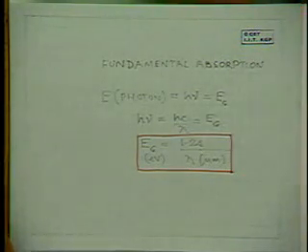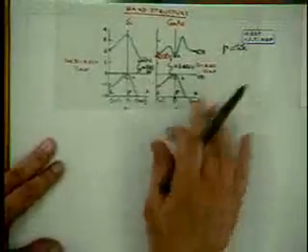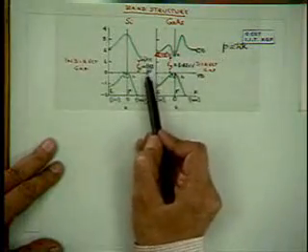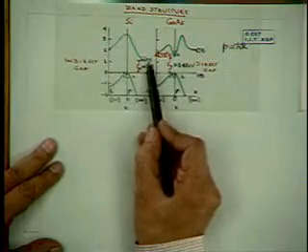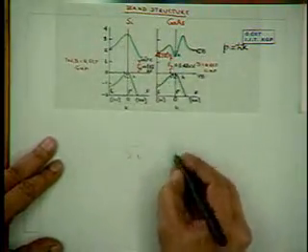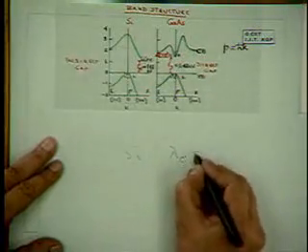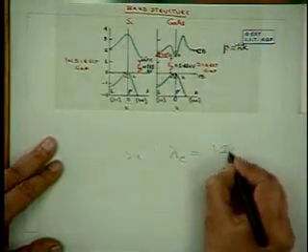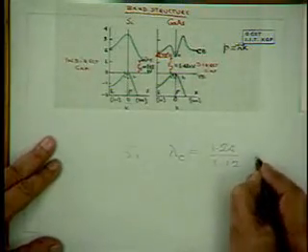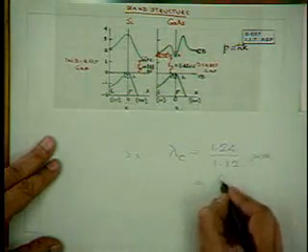Now, as we saw in this energy band diagram, for silicon, the band gap is 1.12 eV, so the direct absorption edge is given by, for silicon, lambda c is equal to 1.24 divided by 1.12, that is about 1.1 microns,